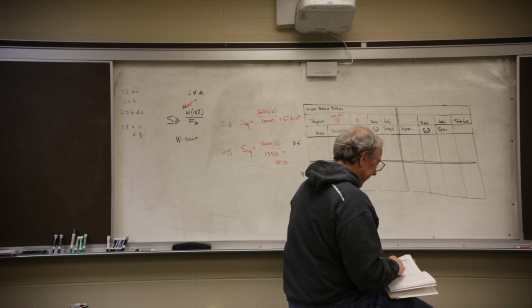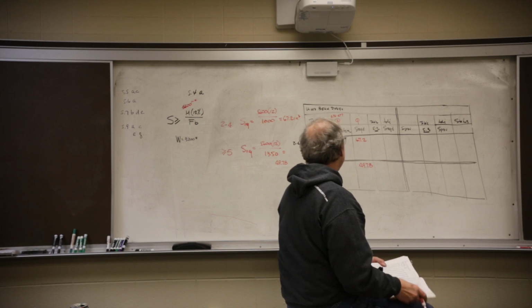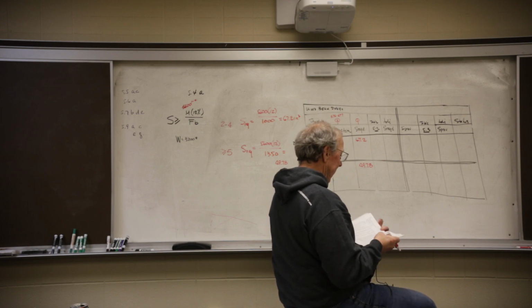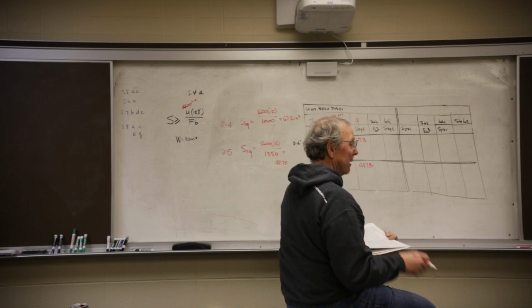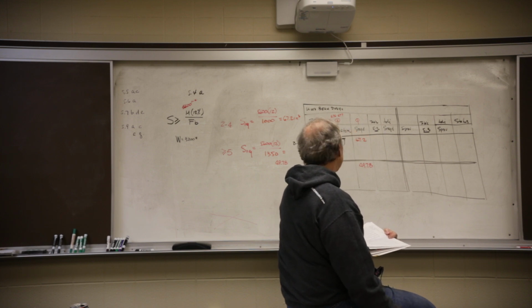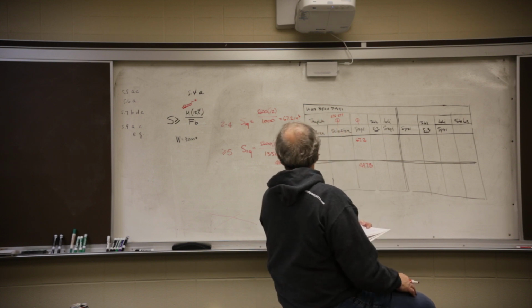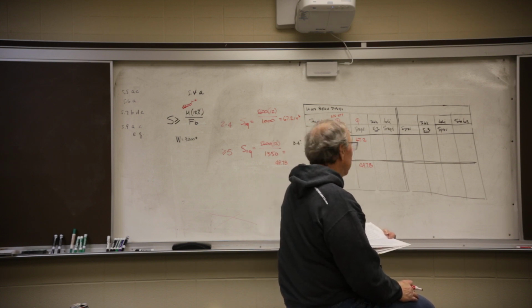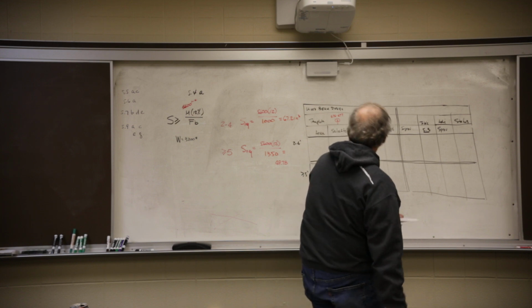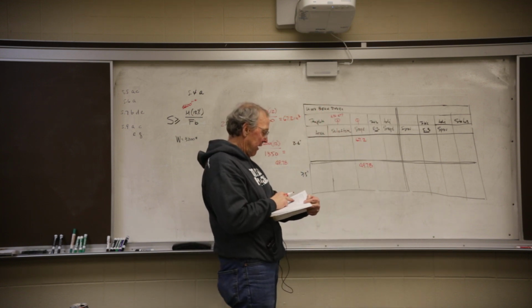I'm going to start running down. And I'm going to pick members that have a section modulus equal to or very close to 67.2, and the inequality says it needs to be a little bit bigger. So it's got to be at least 67.2 or a little larger. So put your finger there.